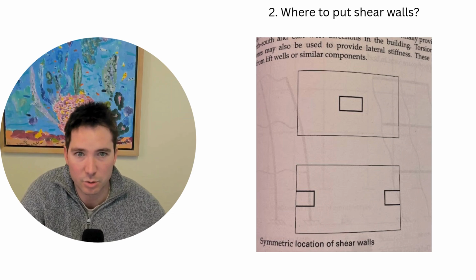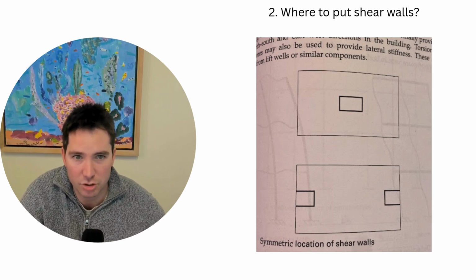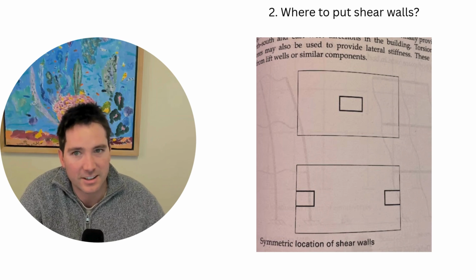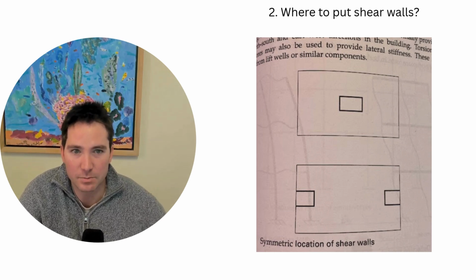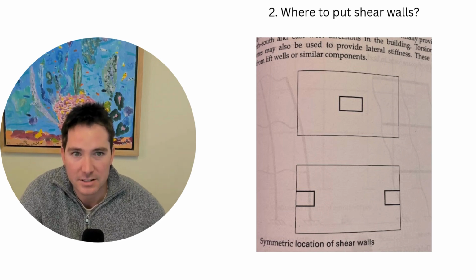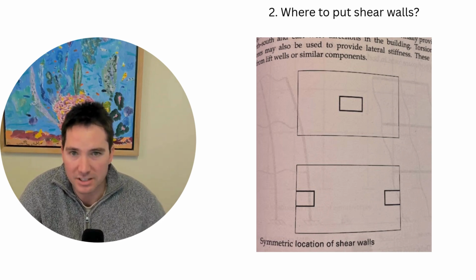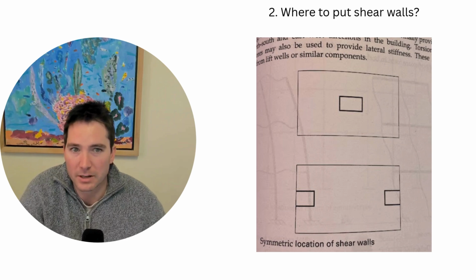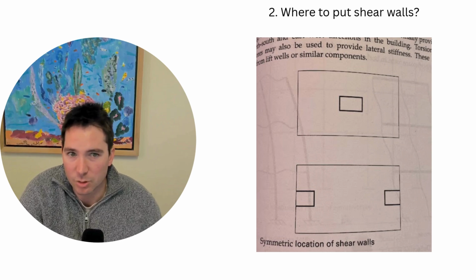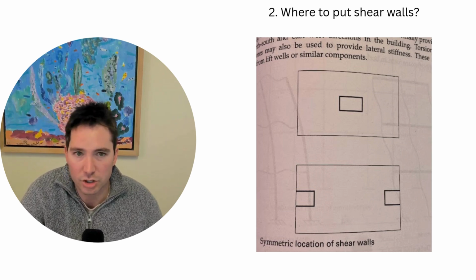I won't go into too much detail there because I'm just trying to do the engineering in the fast lane method here. But where you place them, you're going to put them around voids. That's the most logical and sensible place to put them, and that's where you typically find them. And if you're working with architects who want to put them in places, they're not going to be thinking about the torsional effects of where your shear walls go.